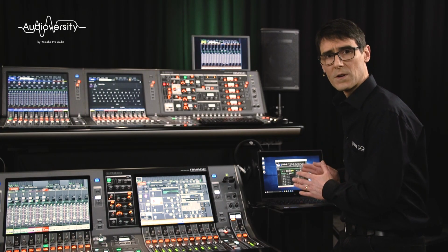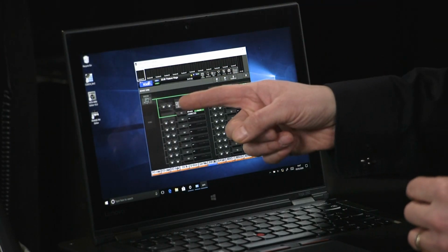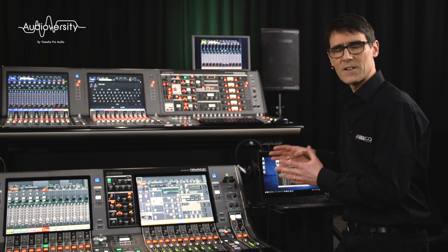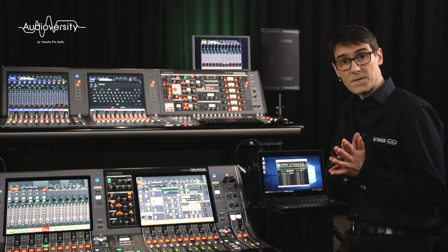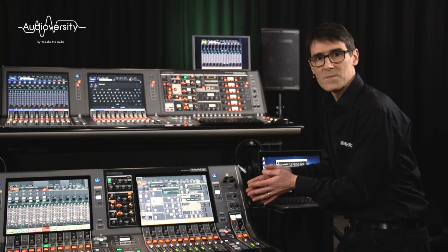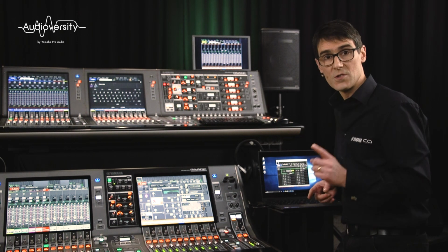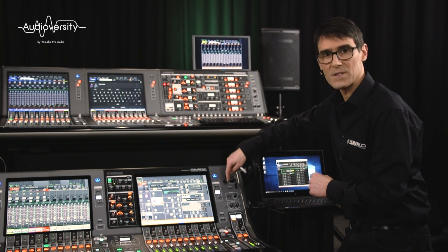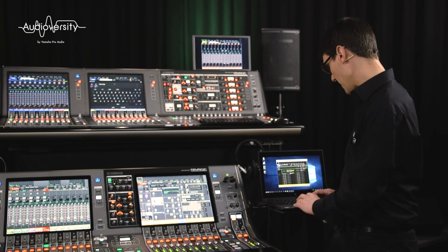When you first go online, you'll need to choose a sync direction. Do you want to receive the data from the DSP and console, or do you want to transfer the data from the editor and overwrite the console and DSP settings? So choose carefully. If you're not sure, save the settings from the console onto a USB drive first.